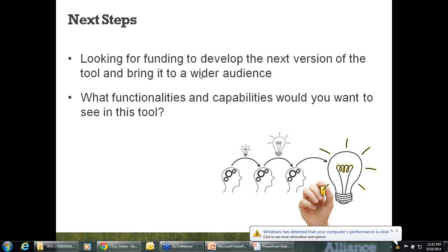But the tool has another aspect to this where we're looking at, in a higher performing home that is airtight, what happens in the interior environment in regards to dehumidification. So the dehumidification side of this tool looks at hot, humid climate zones, and how those higher performing homes address dehumidification of air. To give you a brief overview, the inputs are the volume of the house, the amount of infiltration calculated by a blower door test, the capacity of the equipment, the actual loads of the home in regards to heating and cooling load, and it asks for ventilation rate in regards to 62.2.